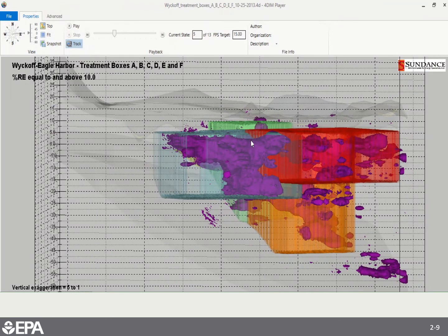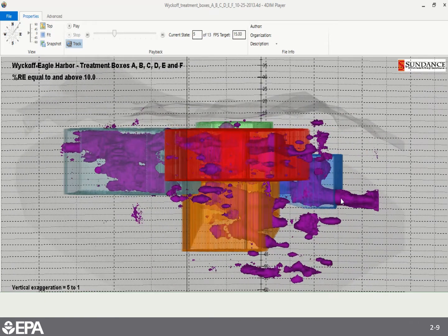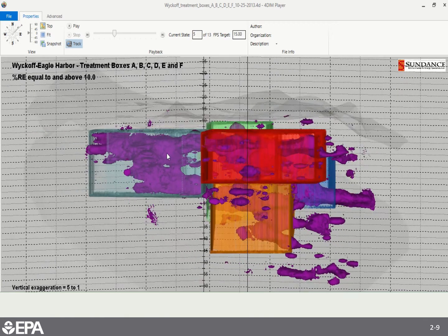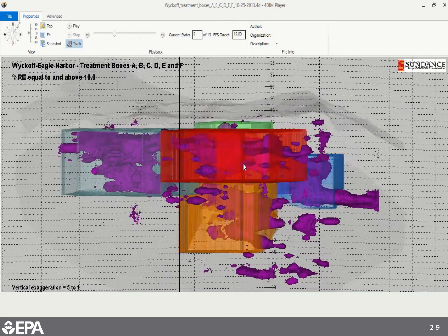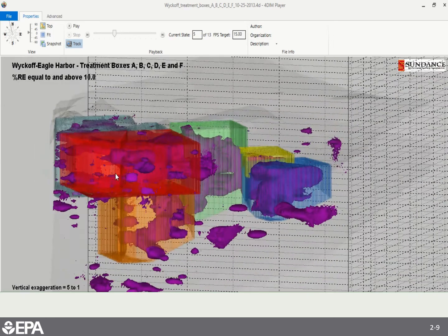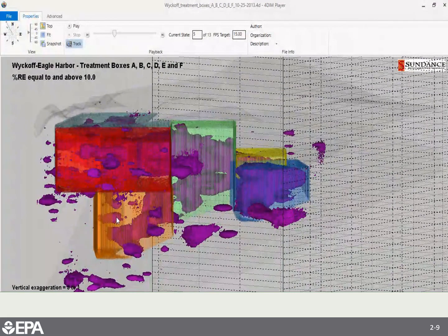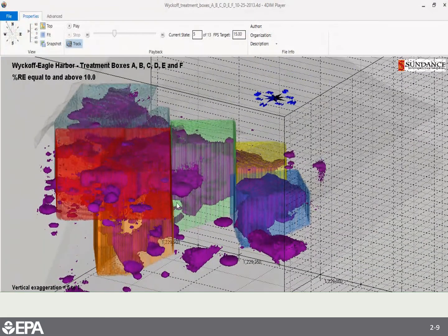This material tends to have an LNAPL or a lighter signature than some of the materials that you would find, for example, over here along the aquitard, which tend to have much more of a DNAPL signature. So it's a complex mix of TPH that's been spilled and moved around and transported across the site over the 100+ year history. And we were able to come back in with this technique to try to see if we could visualize all of the different distribution of the NAPL and look at technologies and volumes of material that we might need to treat with those technologies to understand costs.